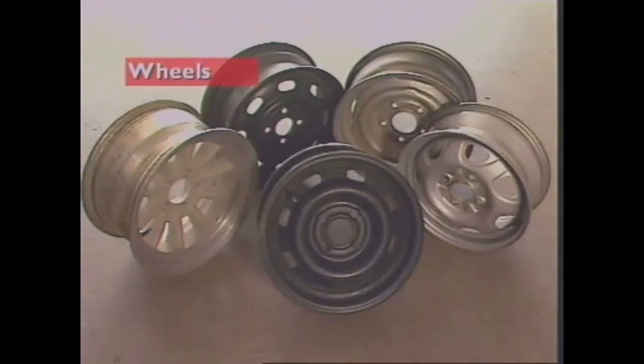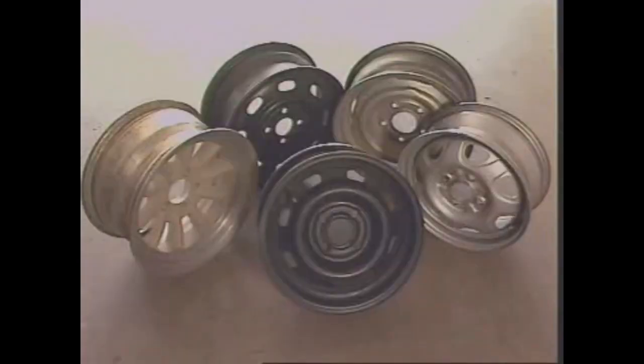This section examines wheels. Wheels must be strong enough to support the vehicle and withstand the forces caused by normal operation. At the same time, they must be as light as possible to help keep unsprung weight to a minimum. Wheels can be made from pressed steel in 2 sections: the flange or disc that is drilled for the wheel fasteners, and the rim.